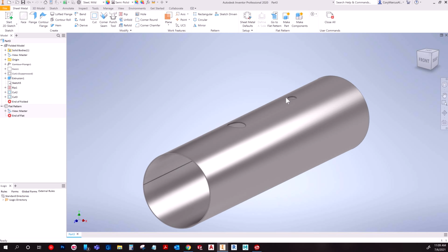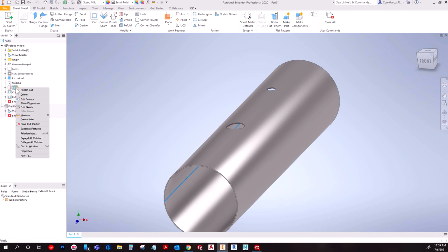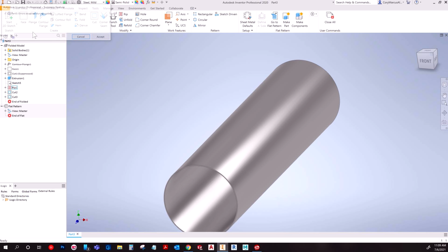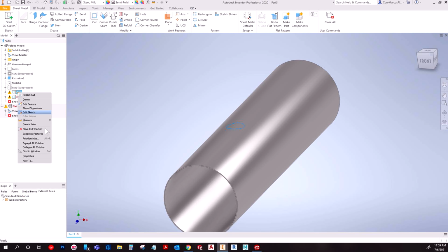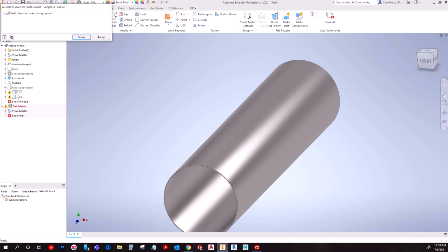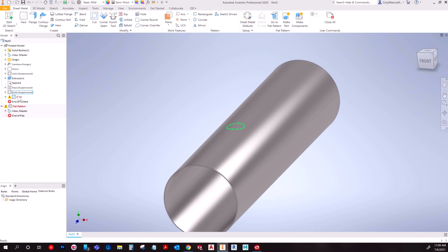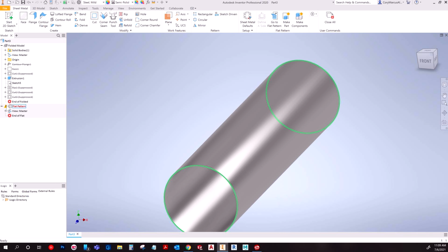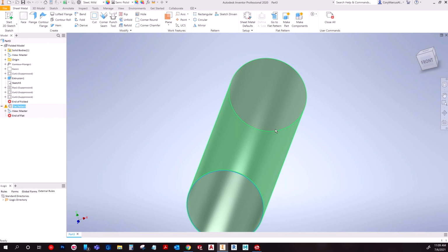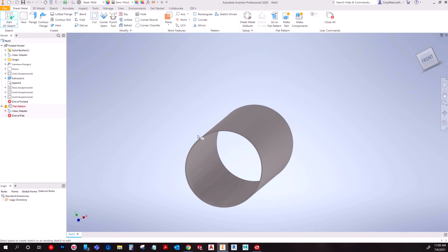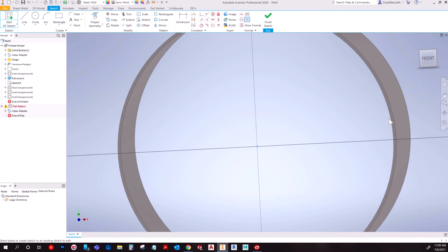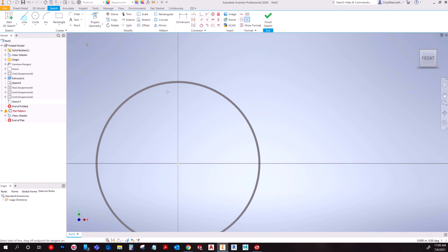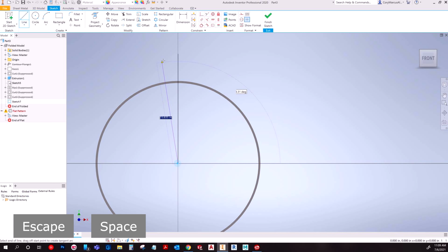Now, that's pretty cool, but say we didn't have this rip. I'm going to suppress it and it's going to scream at me. It's going to keep screaming because now we can't have a flat pattern. What's cool is you can ignore that the flat pattern's broken and just keep moving on. You can also just click on it and delete it and then add it back with the click of a button. But I wanted to show how you could do a rip manually, for whatever savage reason. You could do something like this.